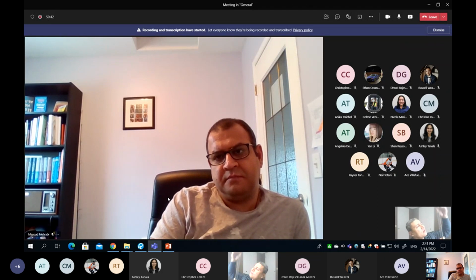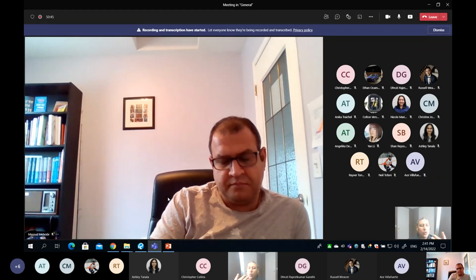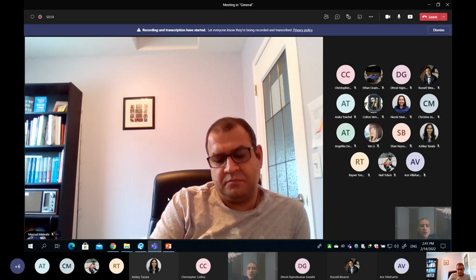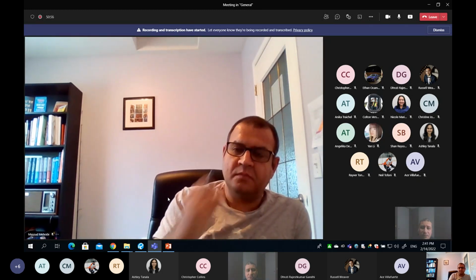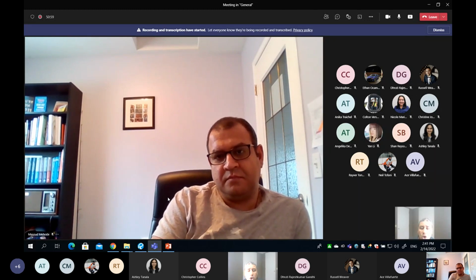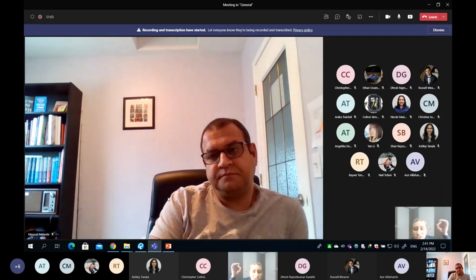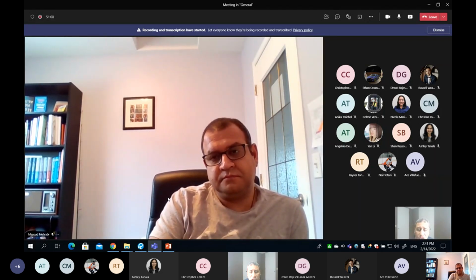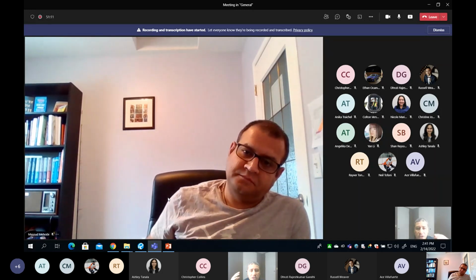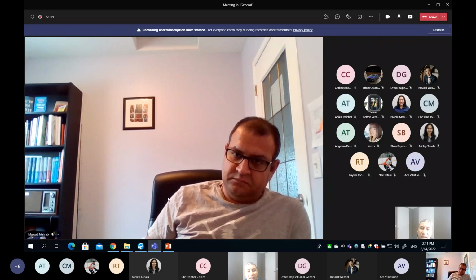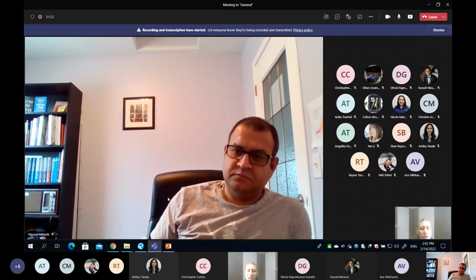Look at this. Why does the buckling happen? Remember, look at the ruler. One is wide, strong, and the other one is narrower and weaker. You can see here. Look at the buckling. It will always happen on the weaker axis. This is something you will learn about with Ramin in the course, called slenderness. It's not about height only, or about cross-section area only, or dimensions of the cross-section. It is a combination of both, something called the slenderness ratio. The more slender our member, the more it suffers from buckling. Now, look at our member.